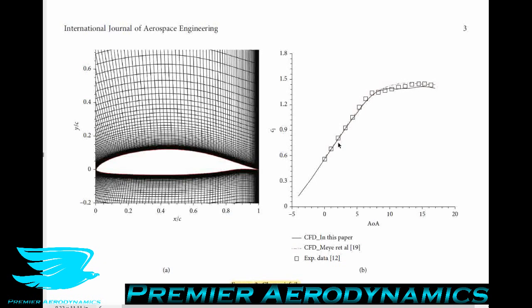And the maximum lift coefficient we achieve here is about 1.35, 1.4, which is a little bit higher than I found in some textbooks, but those textbooks only went up to like 250,000 Reynolds number, so this is 1 billion Reynolds number. So that makes sense that we get a slightly higher lift coefficient. So we get good agreement here.